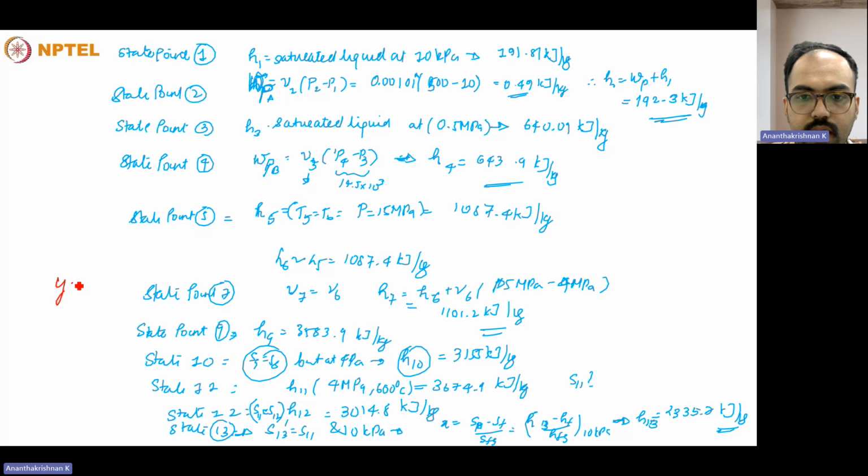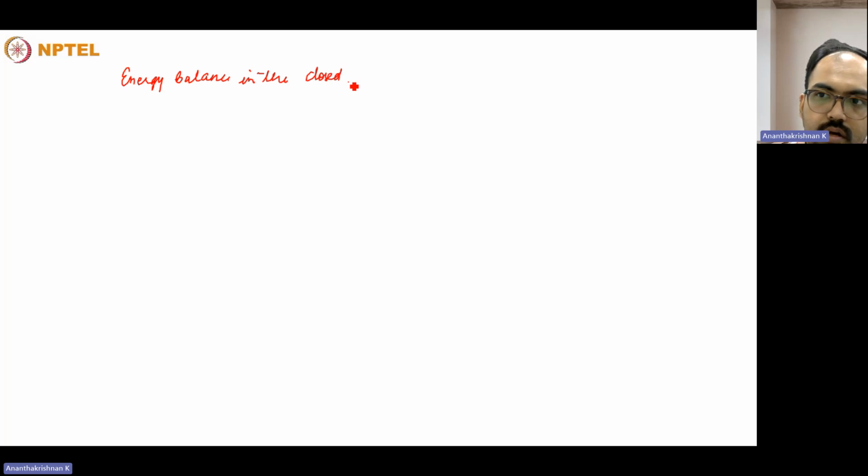So Y, Z, and H8 are the unknowns. Based on three energy balances, we can get them straight away. The first energy balance is the energy balance in the closed feed water heater, that is the top feed water heater. So that comprises only of the fraction of the steam Y.